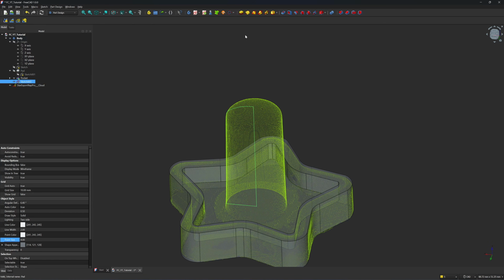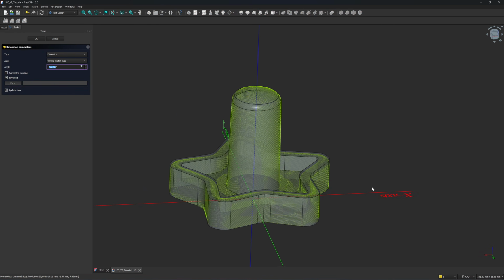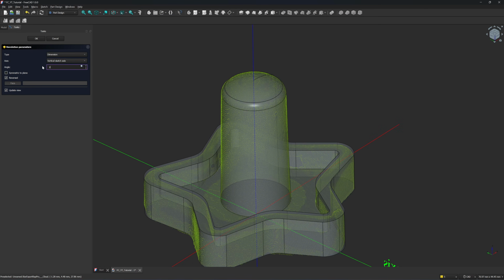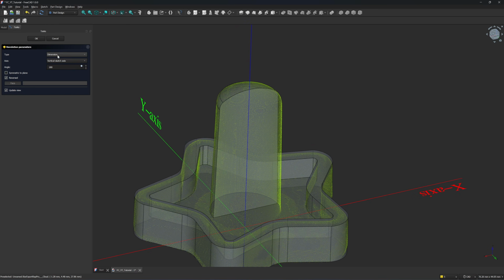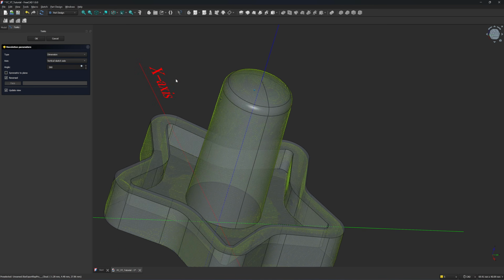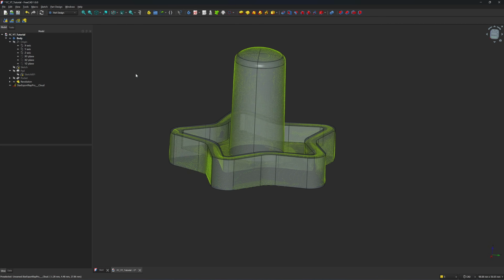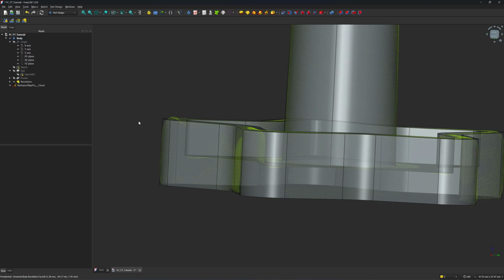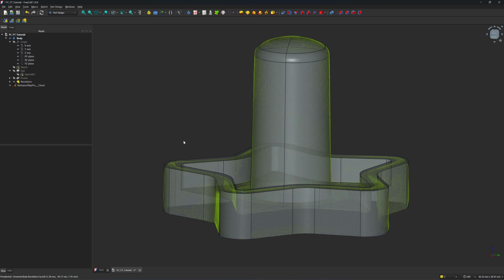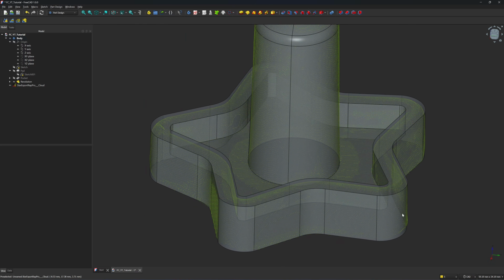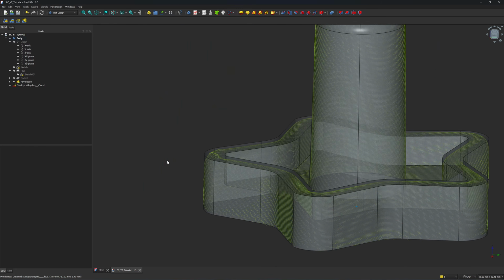Click on revolve, all right? If the line is closed, it will start to revolve. Yeah, let's try half revolve. Okay, this is half revolve. So let's try 360. Okay, full revolution. Click on OK. Now it's fully revolved. Okay, next I'm going to do a fillet, but I'm going to print this in this direction, so I think I'm going to use chamfer instead of the fillet because it will look better.